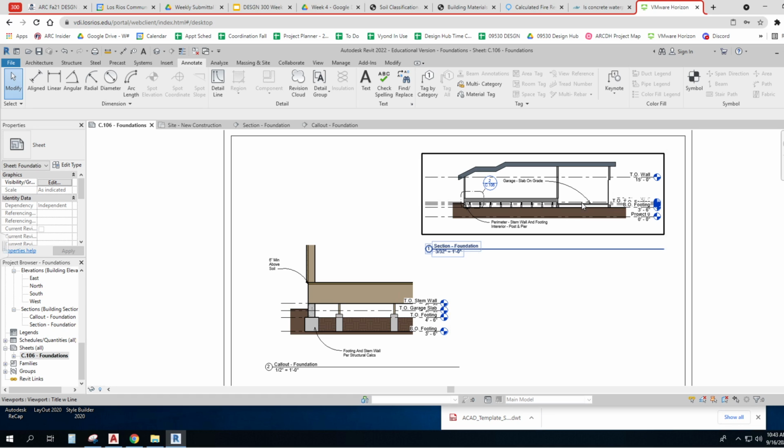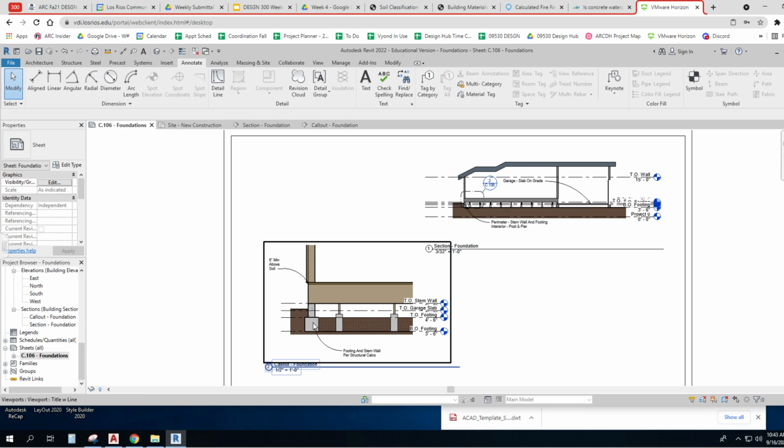But that is prone to cracking. And so depending on where you are and what the surface is like, you might get it poured in 10-foot by 10-foot segments, or 4-foot by 8-foot segments with a border around it. It's hard to tell what they'll actually do on that. Okay, and it doesn't talk about the finish or anything. So there we go. That's a little bit more. This would actually need even more information that we'll talk about when we talk about floors next week.